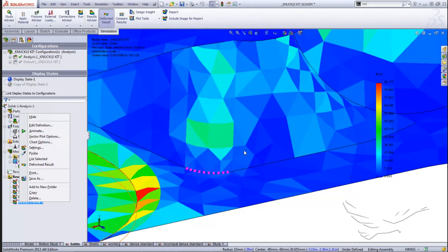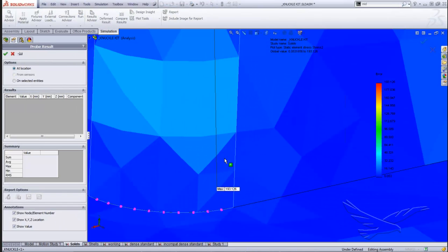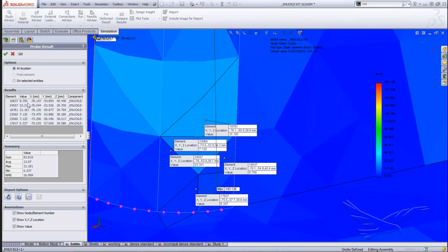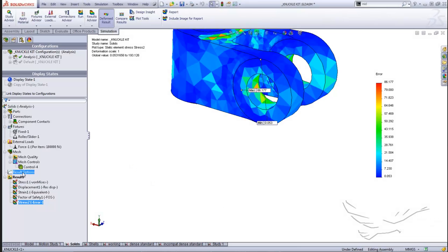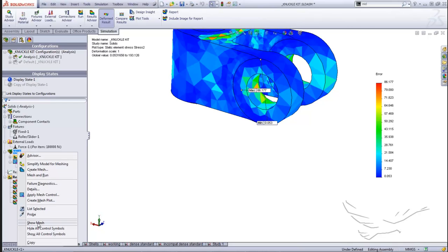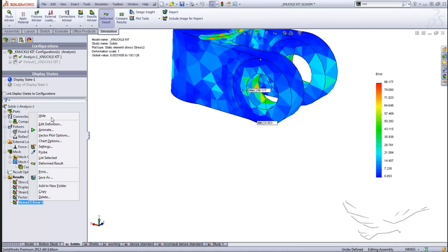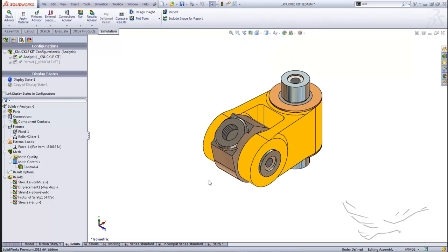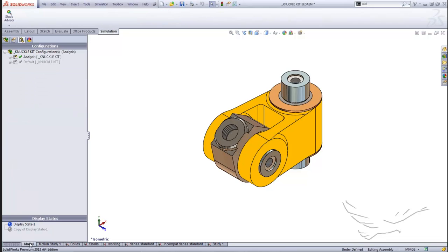And we can look at the error, probe it again. And now they're down a bit lower to the 6s and 7s, but there's still areas where there's slightly higher error, so I can go ahead and further refine my mesh at those locations. So in this example, the model wasn't too tough to mesh, but you can also take a piecewise approach to a model like this when you're having a very difficult time.